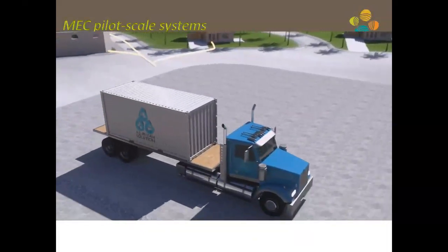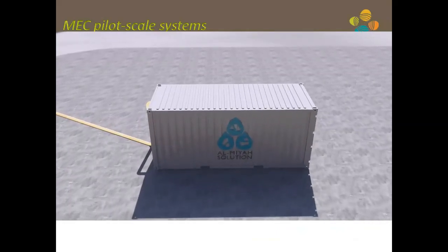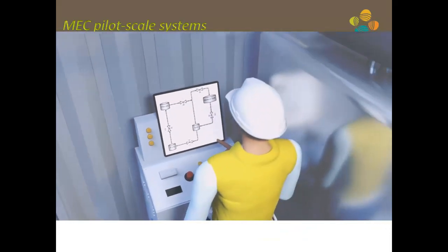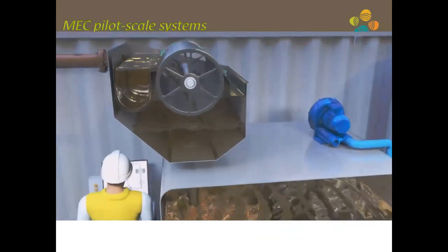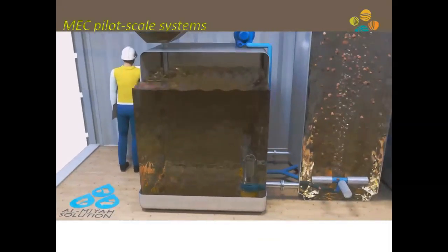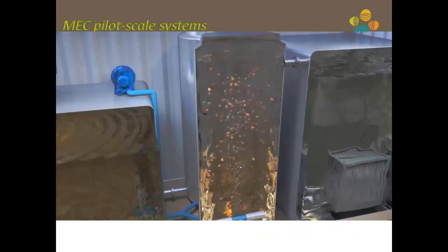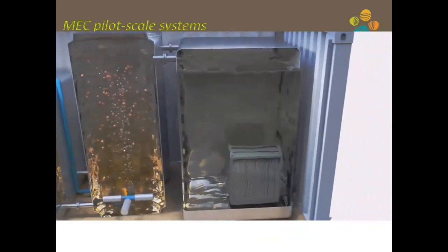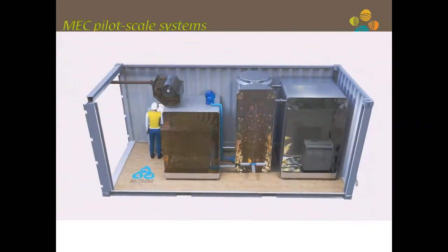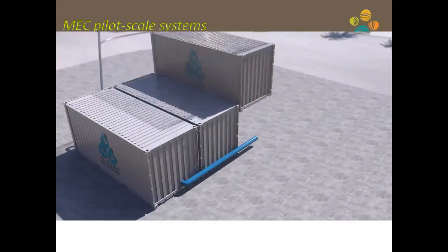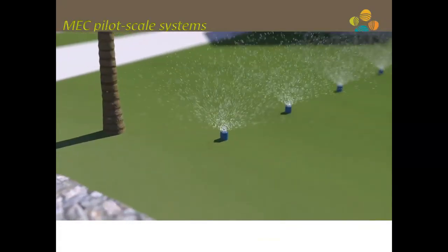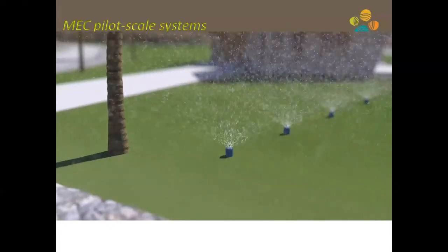As I mentioned earlier, in many parts of the world, development is very scattered, and many residents are not connected with central sewer collection and treatment systems, right? So our aim is to develop decentralized systems for wastewater treatment and resource recovery, which are movable, plug and play, modular in design, and robust in function. As shown here, we can move this containerized technology anywhere, install it quickly, and recover fresh water. This technology is scalable. Whatever water we recover out of this process, we can use for gardening or irrigation purposes.